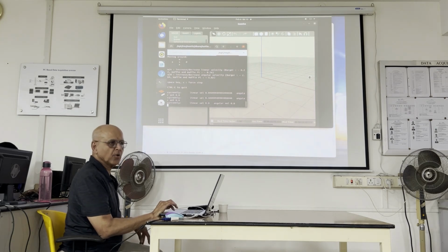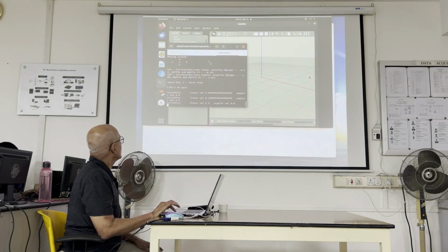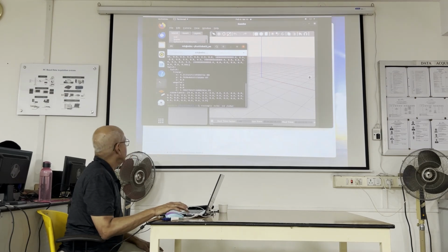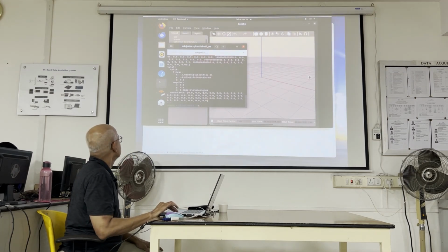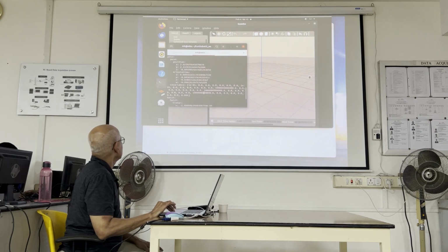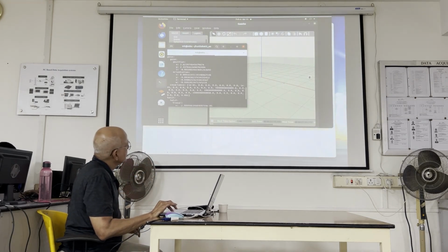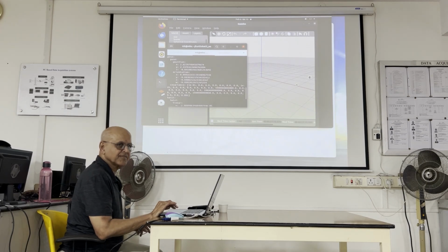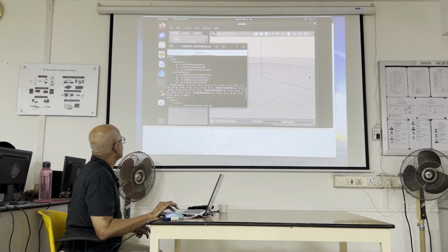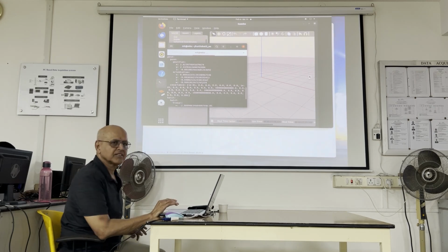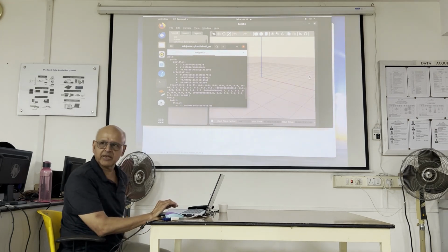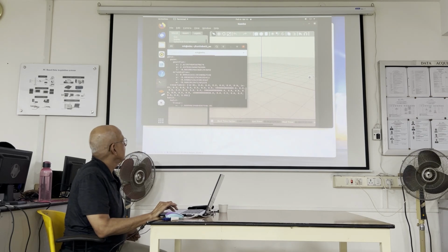So what do you think we're going to do now? We're going to go back to the odometry window, which has stopped running, but I can just cycle back and run the same command. Let's look at not the twist, but the pose. So X is 2.82 with my robot. 2.8, yeah, that's okay, right? Close enough. And Y is 2.43. So you think it's okay? Everyone? Right?